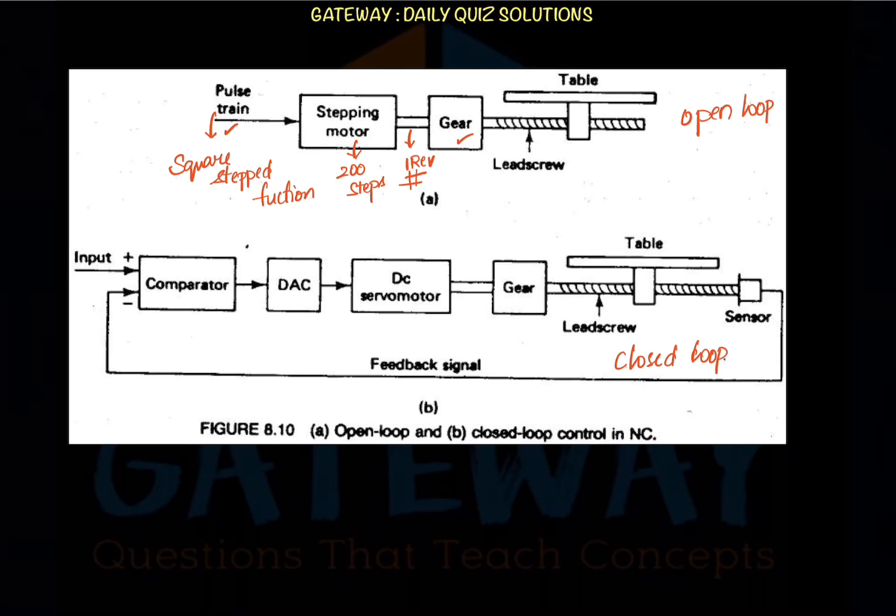We are not giving it only once and leaving, we are continuously giving, right? So this is revolutions per second or revolutions per minute. We will have some speed, and that speed is generally used with a gearbox. For our requirement, if we need high speed, then we will use a speed-increasing gearbox, or if we need reduction, then we will use a reduction gearbox. Depending on that, that power will be given to the lead screw, so it drives the lead screw. Here we create a rotation, and the same is given to the lead screw.